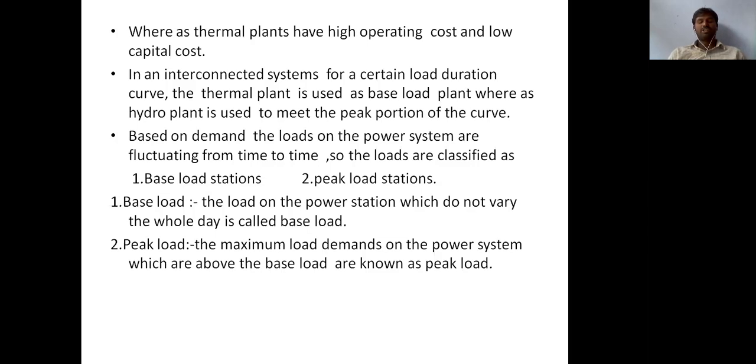The head of the water in the reservoir is generally high during the rainy season. When very high usable water is available in the reservoir, only then can a hydropower plant be treated as a base load plant.